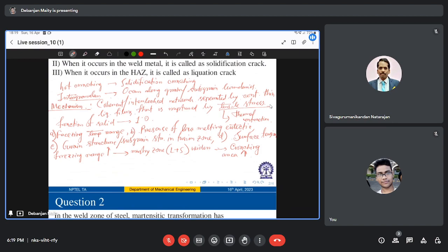For example, in aluminium alloys, sensitivity to solidification cracking is greatest at intermediate levels of common solute. This is because at very low level there is very little effect on the freezing range, and little or no tendency to form cracks, since pure aluminium is resistant to cracking.